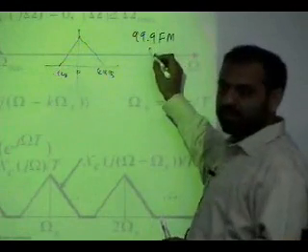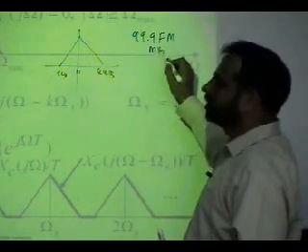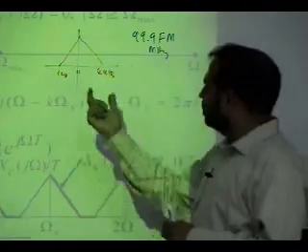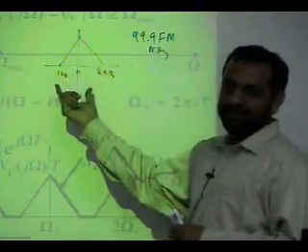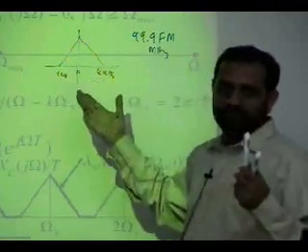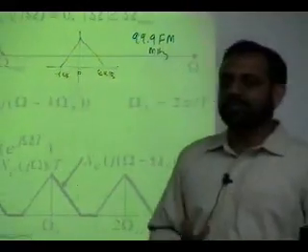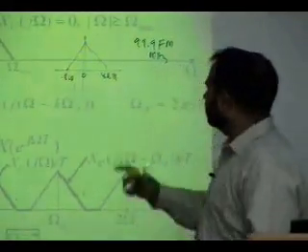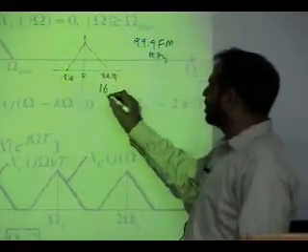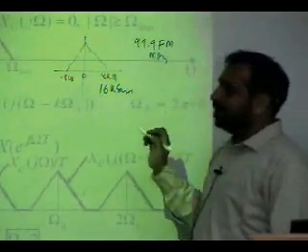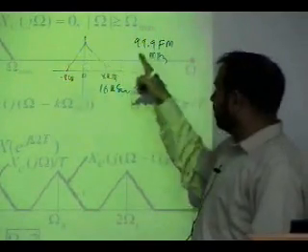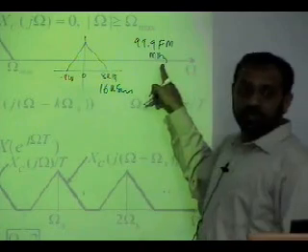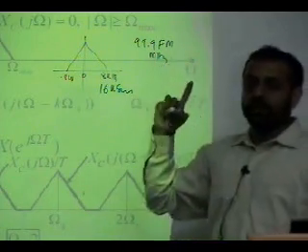And 99.9 FM is at 99.9 megahertz. The actual voice is only this, which requires how many, what is the sampling rate? Just say 16 kilo samples per second. So this voice only requires 16 kilo samples per second. But just to take it from here to here in the digital domain requires 200 mega samples per second.